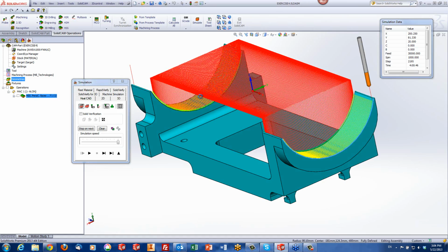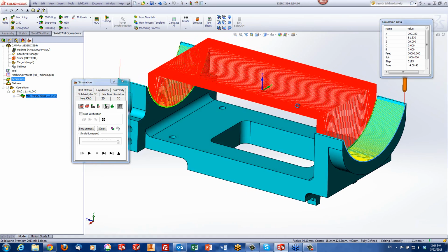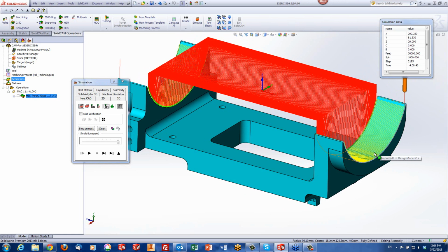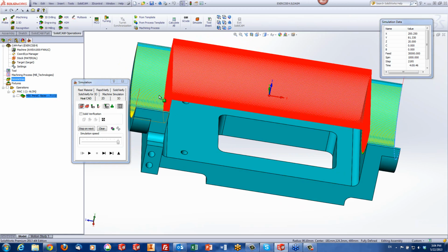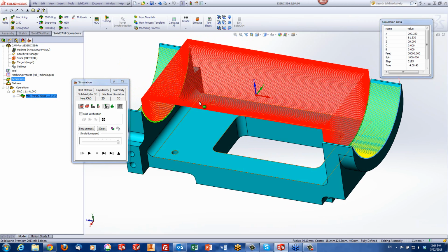Forget about these clearance steps, but I would like to finish off one surface, and then when you finish that surface, go to the next surface, not go back and forth, because you're wasting a lot of time this way. So one way is to do two separate operations: first do an operation on this surface and then do a copy operation on the next surface. Or we can do the following.